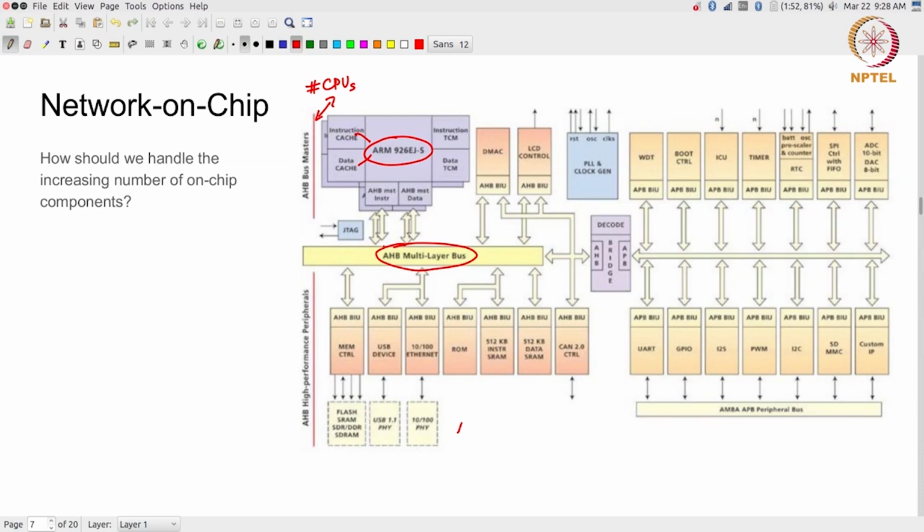But like I said, nowadays, especially with AXI, not so much with AMBA, but with AXI, the newest version of the bus, it has been very widely adopted by a number of other kinds of processors as well. So it's very likely that you can come across, for example, a RISC-V based system with an AXI bus interface. But this ARM processor has access to an AHB multilayer bus. Look at the number of peripherals it has to deal with.